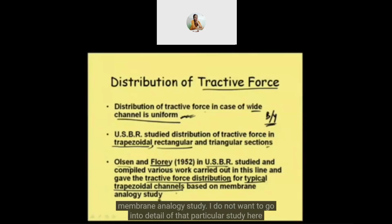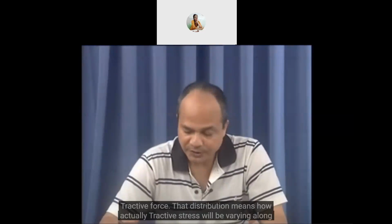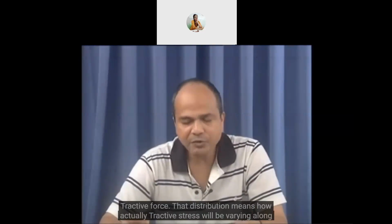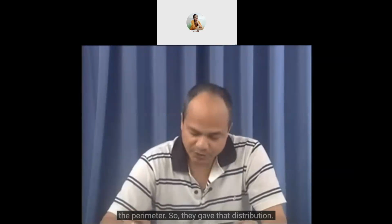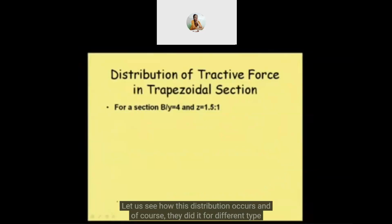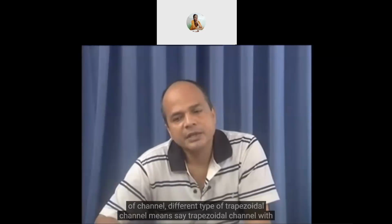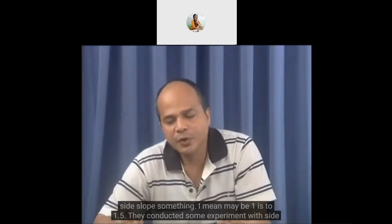Based on a membrane analogy study, I do not want to go into detail of that particular study here right now, but we need to know that based on their study, they gave a distribution of tractive force. That distribution means how actually tractive stress will be varying along the perimeter. So that distribution they gave. And let us see how this distribution occurred. And of course, they did it for different type of channel, different type of trapezoidal channel. Means, say, trapezoidal channel with side slope something, I mean, maybe 1:1.5, they conducted some experiment.